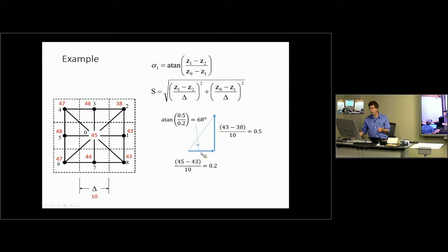So when that's the case, then we have to pick the slope down the steepest edge, which is either the diagonal or the straight edge. In this case, it's the diagonal, this red arrow here. So you would choose the angle to be 45 degrees. You'd evaluate the slope along that 45-degree direction, 45 minus 38, 0.495. So the d-infinity flow direction in this case would be 45 degrees.